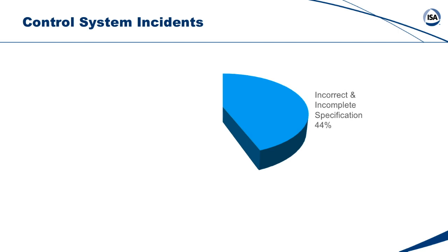I know one example where a safety system shut the plant down and the specification just said all outputs will de-energize, which they did, including the outputs for the lubricating oil pumps on the turbines, meaning the turbines self-destruct when they spin down, and now you can't run your process anymore without your turbines. So the system did exactly what it was programmed and configured to do. There was no failure of the system. There was a failure in the specification, because any system could have had those outputs fail on or to a last state. This still remains the majority of problems with systems today.